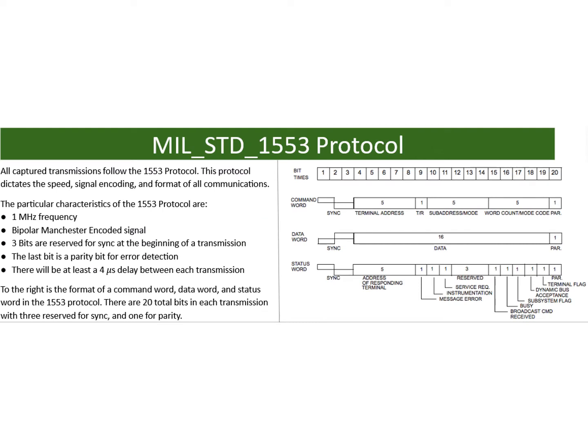The entire project was surrounded by the Military Standard 1553 protocol. This is a 1 MHz frequency protocol that's used amongst avionics equipment. It is a bipolar Manchester encoded signal, and it uses 3 bits for syncing, additional bits for data, and further bits for addressing and other purposes.